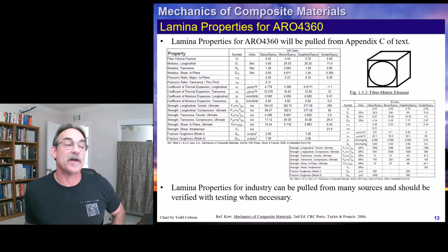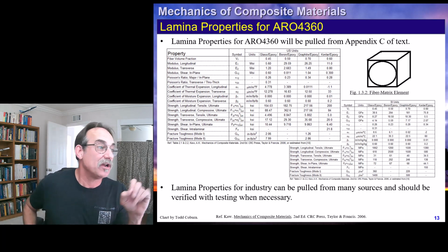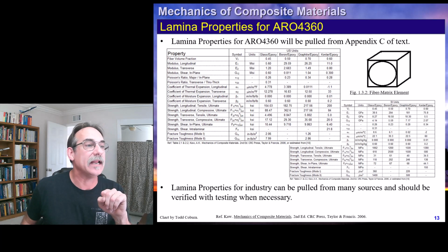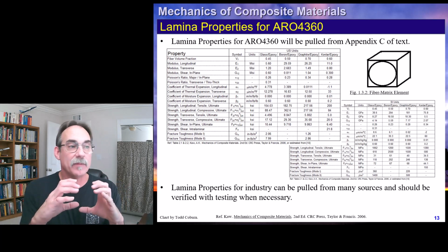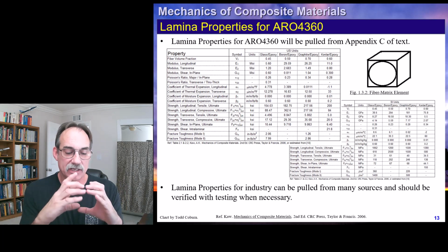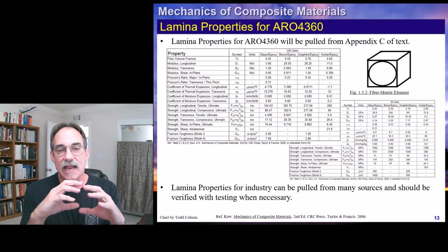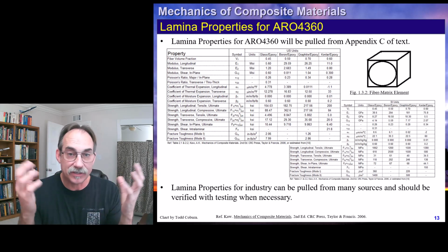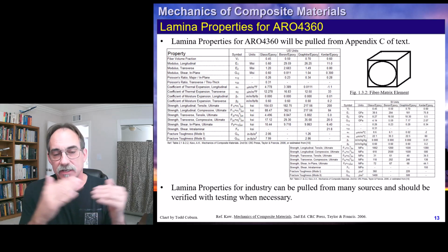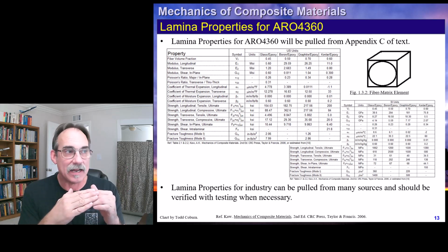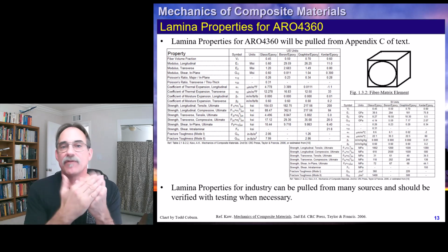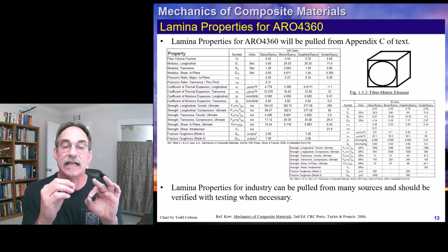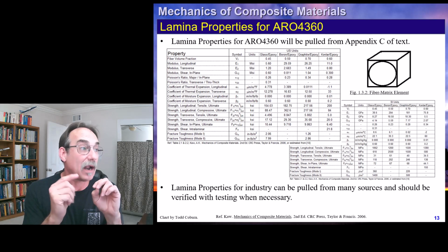If you want a little more information on that, and you want to look at some of the examples he has, go ahead and grab a copy of his book, and that can give you some further reading. A lot of times we're going to use a little element symbol like this in the upper right corner, where it looks like we've got the fiber represented and the matrix represented. What we're trying to show is that we've got a fiber and a matrix, two distinct properties. But actually, once we construct this layer, this lamina, it's going to be like the whole thing. Everywhere is going to be the ratio of fiber and matrix, and we can pretend like it has the orthotropic properties that are given here.